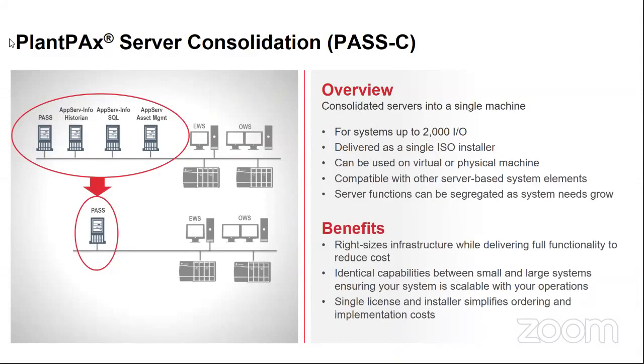What that does is the PAS, the Process Automation System Server, is a virtualized template now running on Windows 2016. We provide you a hard drive with a virtual template that you can dump into VMware or Hyper-V, with the Windows operating system and the actual application already preloaded. It doesn't have any of the code that you would set. That's your job. All we're doing is setting the guidelines so you don't have to install anything from scratch. No more DVDs or Blu-rays or anything like that. We give you one for each one. As of 4.6, we released a full set of images that are all running on 2016.